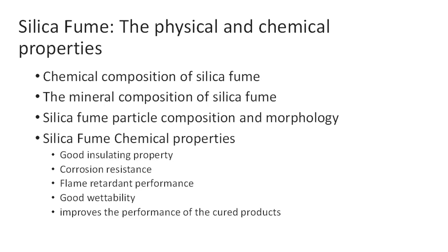Improved mechanical properties. Silica fume's granular gradation helps reduce issues like precipitation and delamination. It can enhance the tensile and compressive strength of cured materials, improve wear resistance, and even increase thermal conductivity and flame retardant properties.